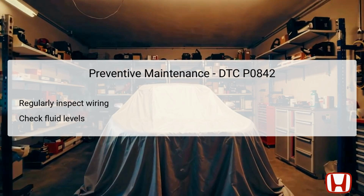To prevent a recurrence of DTC P0842, implementing preventive maintenance practices is essential. Regularly inspect the wiring associated with the transmission system to catch any wear, fraying, or signs of short circuits before they lead to failures. It's also imperative to routinely check and maintain proper transmission fluid levels.